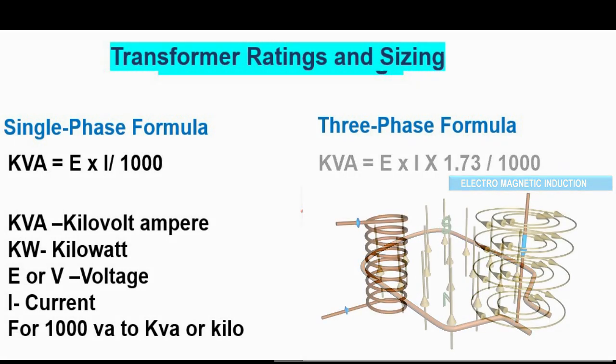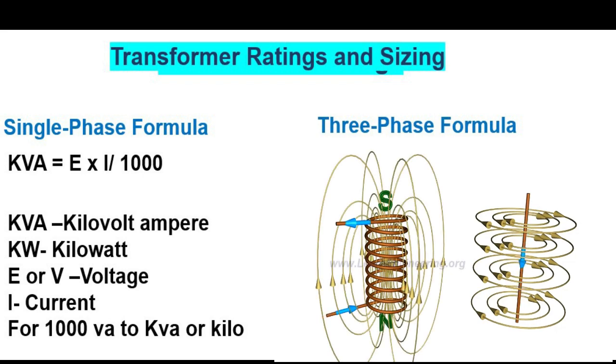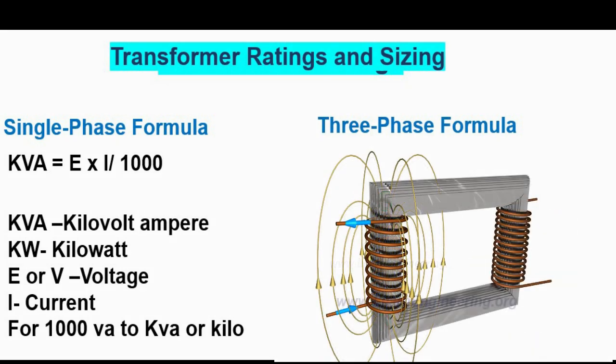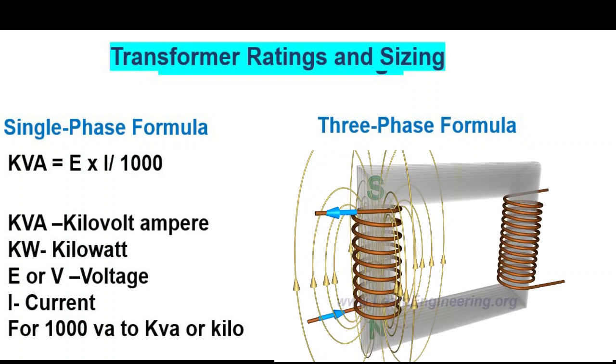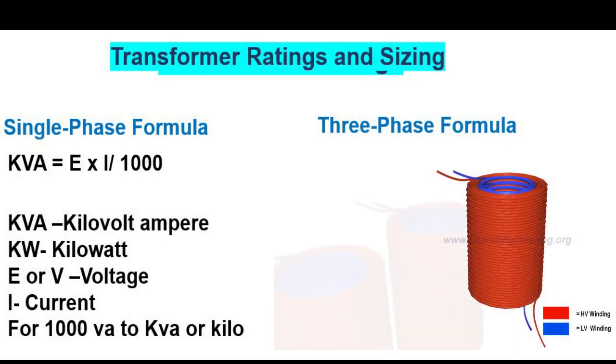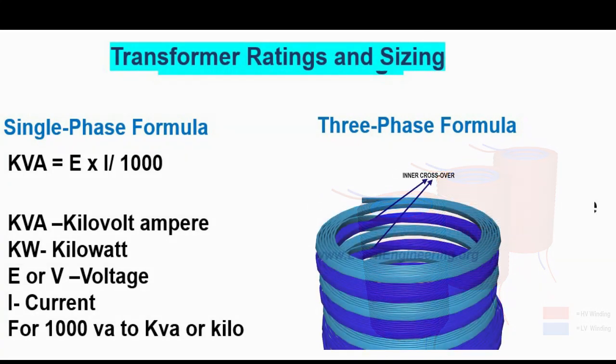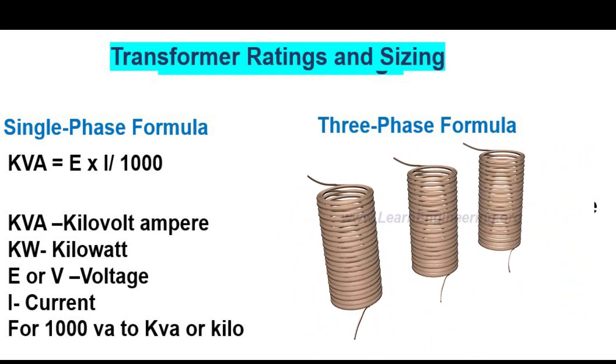select and size transformers. The formula for finding the required kVA or transformer size for single-phase power is the following. Companies or businesses that require three-phase power need to add an extra component in the formula to arrive at the correct transformer size, namely the square root of 3, or 1.732.